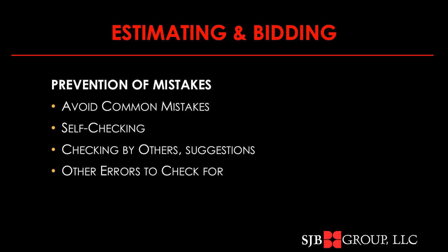If you've got a large bid, you're going to want to pull everything together ahead of time, like a whole day, the night before, perhaps, to ensure that your bid's in good shape. You'll want to recheck all your plug numbers. A plug number is a number that you've written in early in your estimating process when you didn't have the actual price, that you know roughly what it's going to cost, and it's a place saver to get an amount of money in your estimate as you're waiting for that supplier, that subcontractor to provide you the particular number for this project.